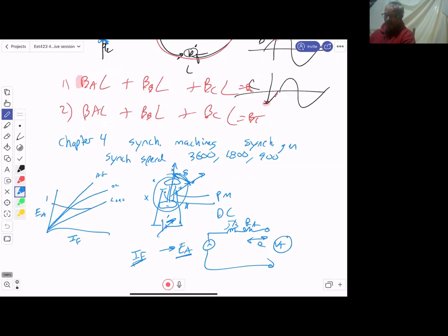This one would be plotted against IA, right? That's the only curve that should be plotted as a function of current. And with that, we were able to calculate XS, the synchronous reactance, both unsaturated as well as saturated. And for your own edification, if you wanted to look, you can actually see where our saturated reactances, there was a direct and a quadrature axis impedance that was provided in those data sheets. The values that we got were pretty close to what they had calculated. And then that gives us our XS.